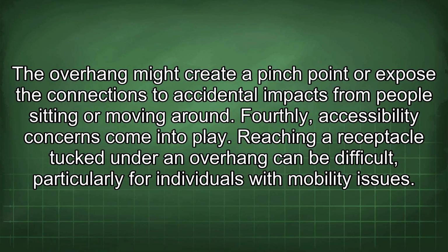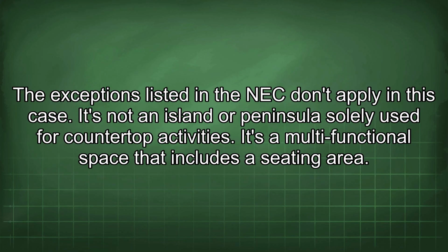Fourthly, accessibility concerns come into play. Reaching a receptacle tucked under an overhang can be difficult, particularly for individuals with mobility issues. The exceptions listed in the NEC don't apply in this case. It's not an island or peninsula solely used for countertop activities.